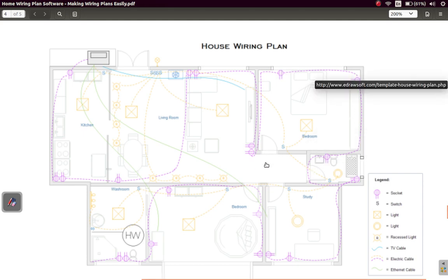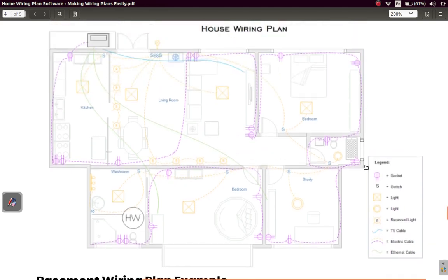The Jamaica standard only allows a maximum of 5 on one circuit, right? But in some countries you can have more, as long as the current being drawn from them doesn't exceed the maximum rating of the circuit breaker. All right.